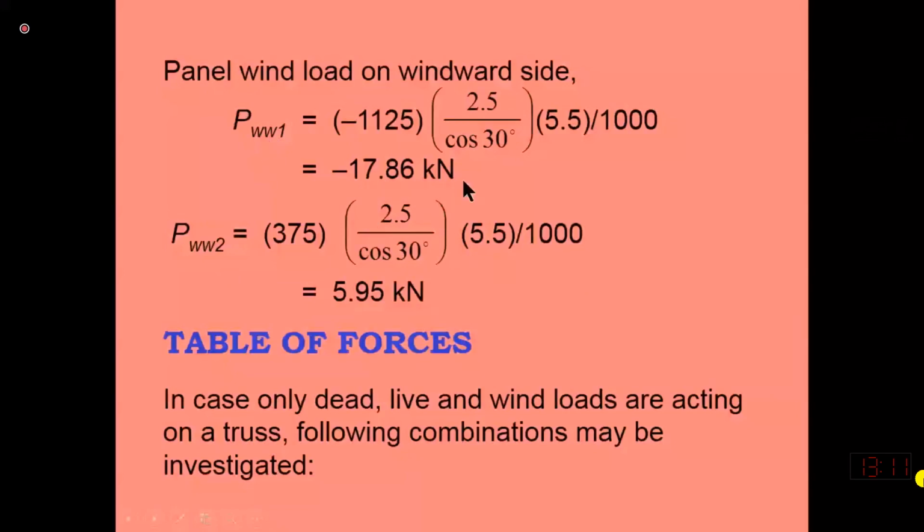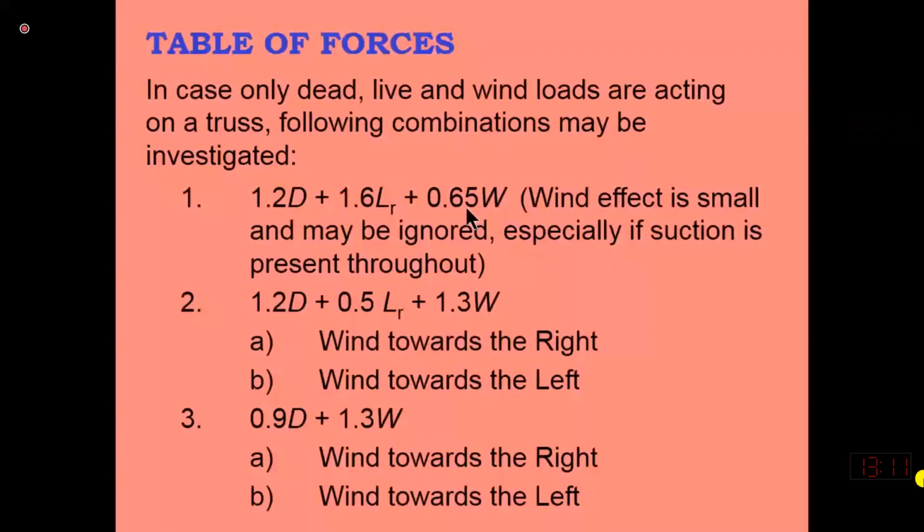Okay, next is the table of forces. In the table of forces, I told you that we have to analyze the truss for different load combinations. Load combination means that all types of wind load, live load, and dead load may act on the structure in different combinations.